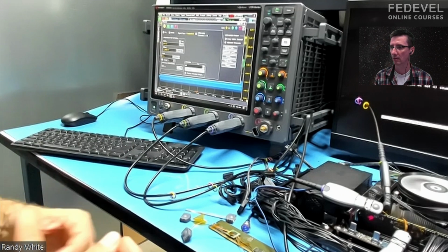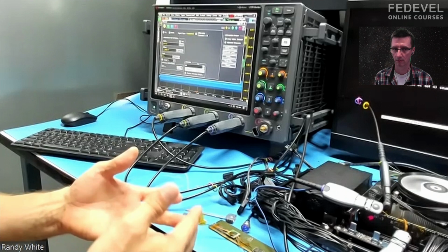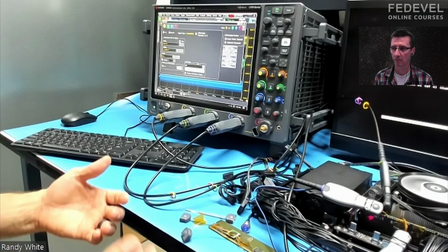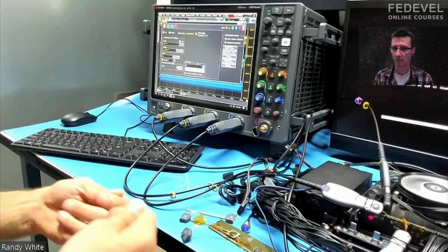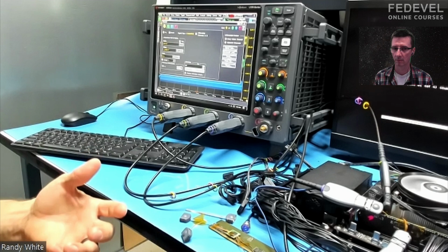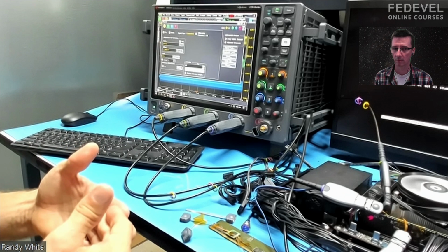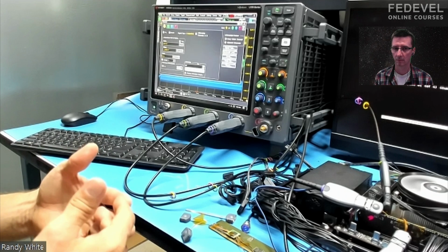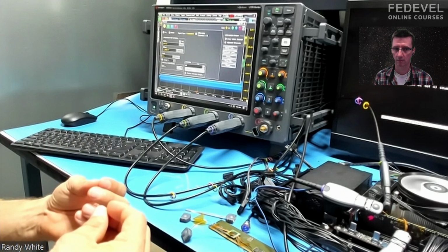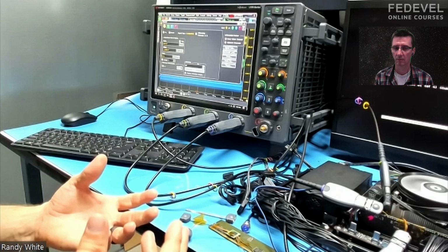So we physically embed the interposer because it has to be there to give us access to the signal, and then virtually through software we can remove that, but we have to know what we're removing first. So that's the S parameter. The S parameter is the model of the interposer response, right?